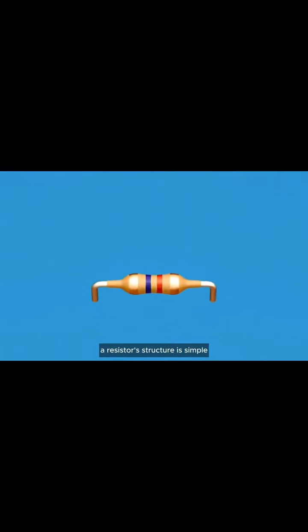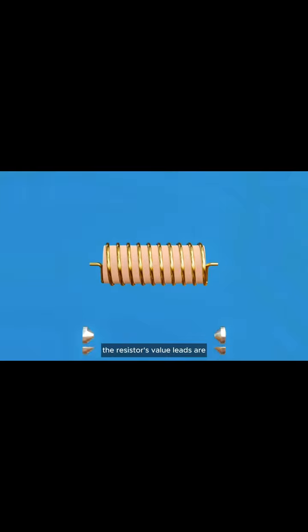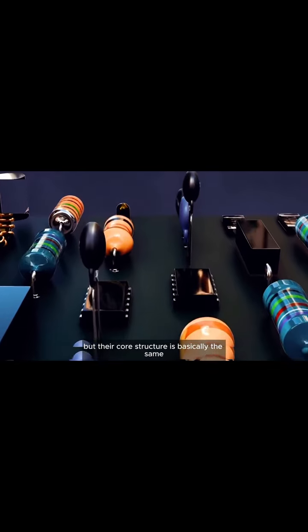A resistor structure is simple. Resistance material is wound around an insulating ceramic rod. The type and length of this material set the resistor's value. Leads are attached at both ends to connect it to a circuit, and all materials are then encapsulated in a plastic or ceramic coating. This is the basic form of a resistor. Resistors come in various shapes, but their core structure is basically the same.